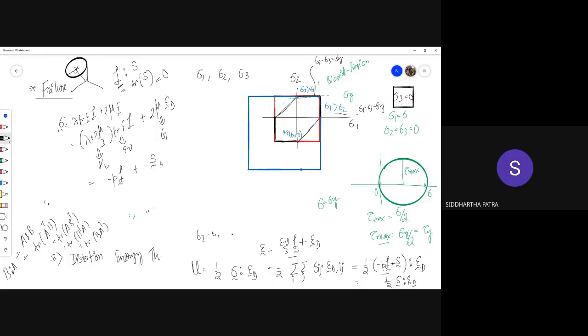Okay, and again, this representation is unique, and we can segregate the deviatoric and the hydrostatic part. So K times epsilon v is minus p, and s right here is twice mu epsilon d, which basically means that this distortion energy right here is mu times S inner product S, or actually 1 by 4 mu S inner product S. Now, if you really think about it, this is 1 by twice mu times 1 by 2 S inner product S.